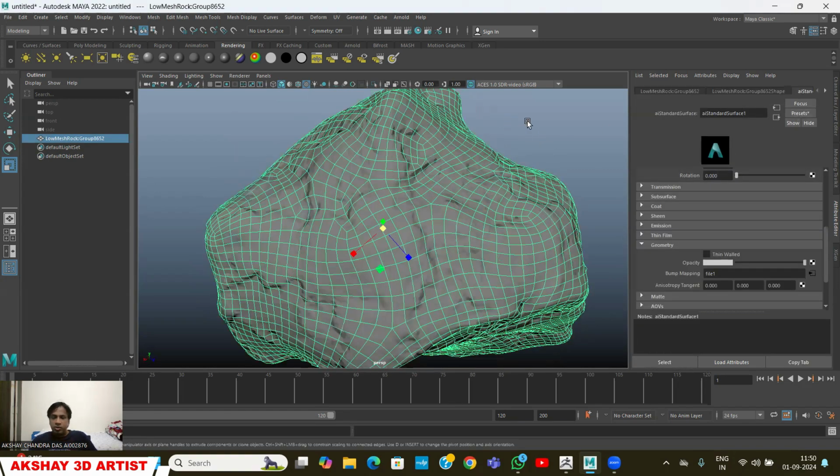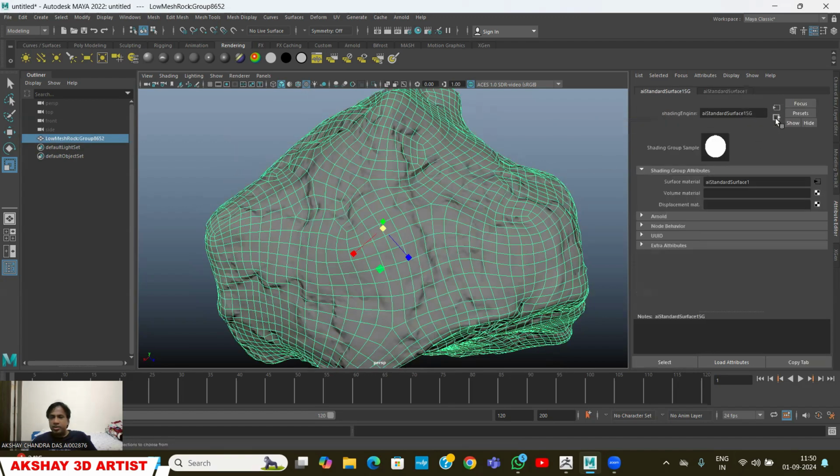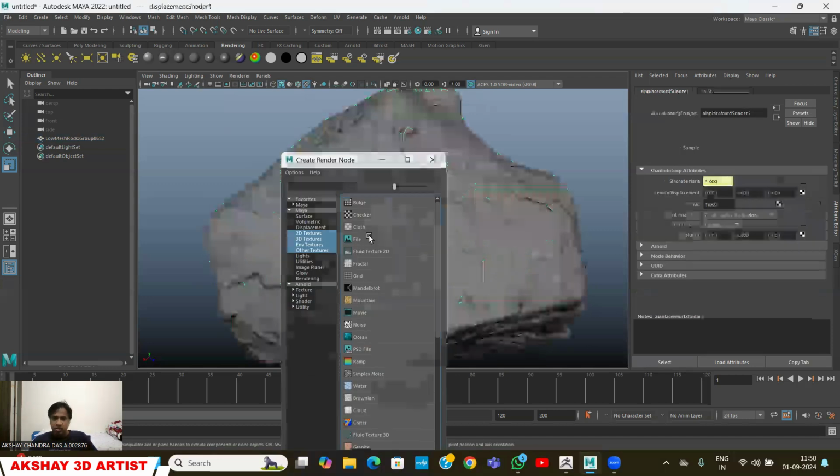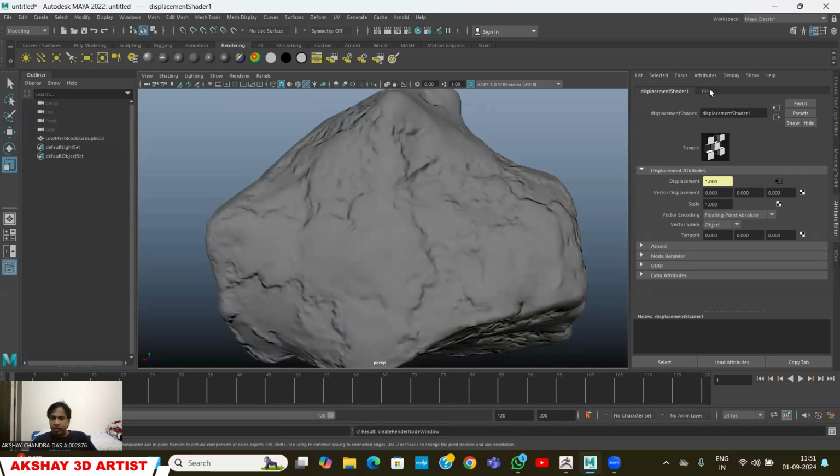So how to use the displacement map? Here you can see two buttons. You can click this, and you can see your displacement map material. With this click, I can go back like this. In the displacement material, this is the map button you can see here. Click this and browse to the displacement map file.